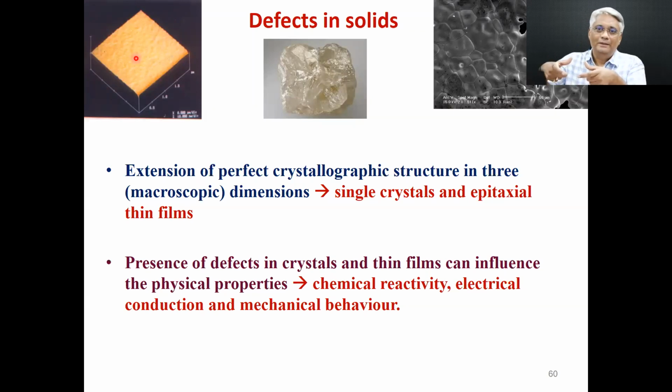I have a base material on which I can grow a thin film, 1 centimeter square, 1 inch square, and the device grade wafers now are 8 to 12 inches in diameter. Crystallinity is there, but the limitation is thickness. You can grow highly crystalline thin films of any material up to a few hundred angstroms.